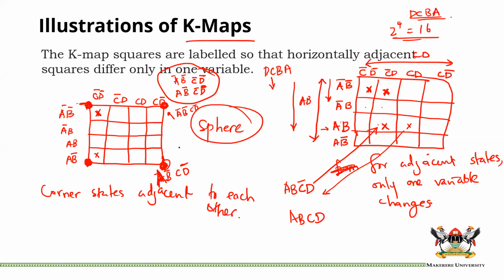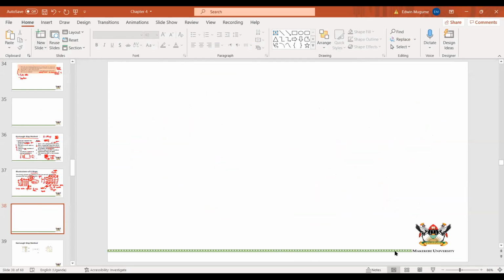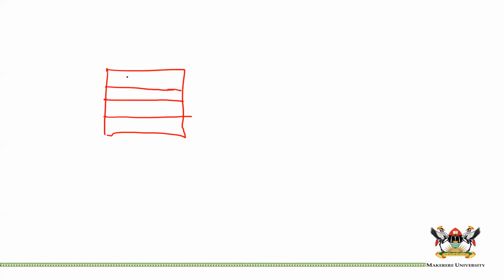We are again going to, this one has actually a consequence, because let me talk about the consequence before we go into the maps. The reason why it has a consequence is because we are going to realize that we are looping ones. I already said that we never put zeros in the loop. Okay, so your loop always has only ones. In fact, that is not entirely true. We also have don't care states that we can loop or not. That will come later.